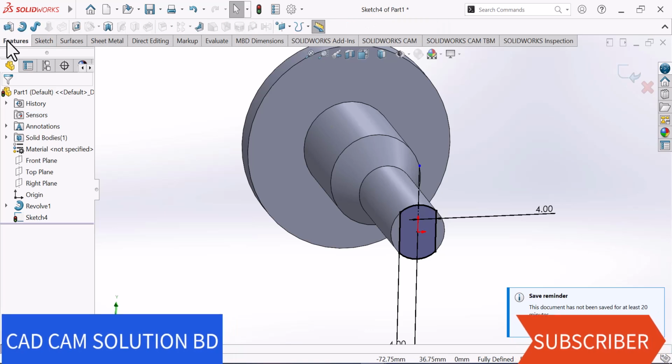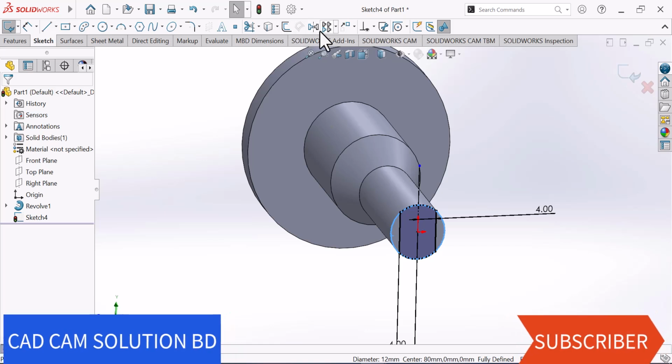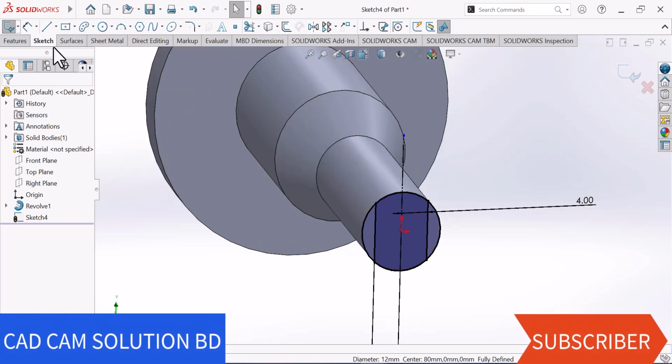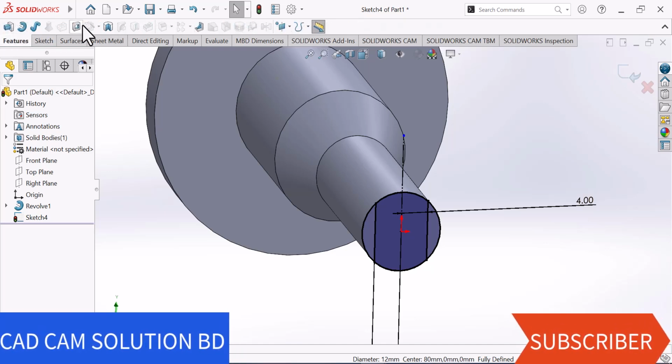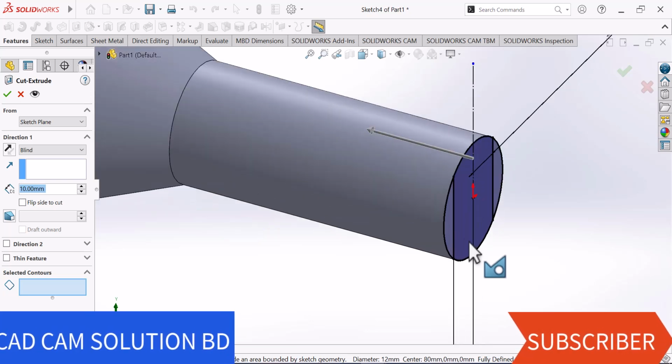Now go to feature. Now select this circle convert entities. Okay. Now go to feature and select extrude cut. Now I need this face.